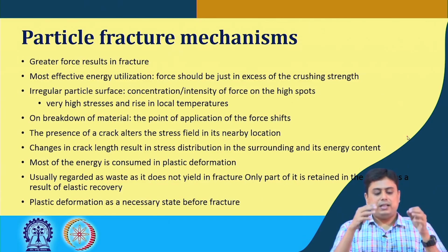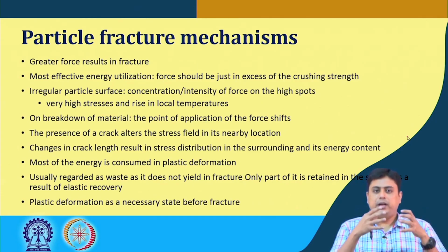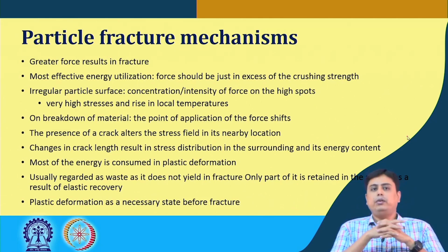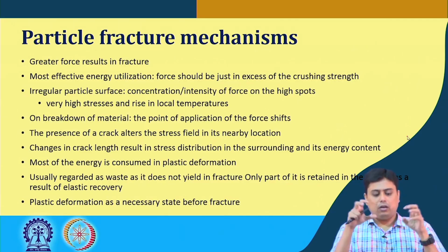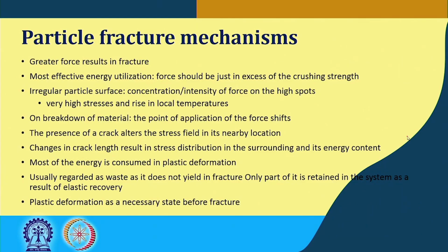So, most of the energy is consumed in plastic deformation, the permanent deformation of the particle, and it can be regarded as waste because it does not result in fracture. Only part of the applied energy will be retained as a result of elastic recovery.